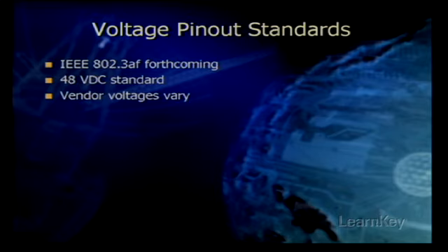Another thing that is very important with pinouts is fault protection. The primary purpose of fault protection is to protect the cable and the equipment and the power supply in the event of a fault or a short circuit. Now, during normal operation, a fault may never occur in a Cat5 cable. However, there are several ways that it could be introduced, such as the attached device simply being totally incompatible with PoE and having some non-standard or possibly defective connection that does short-circuit the PoE conductors. At present, most non-PoE devices have no connection on the PoE pins, and therefore they're not going to have an issue with the pinouts or with fault protection.